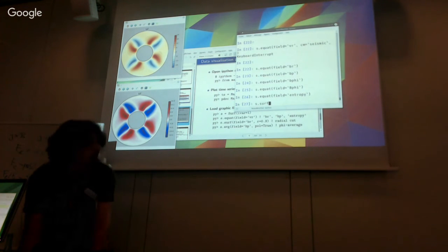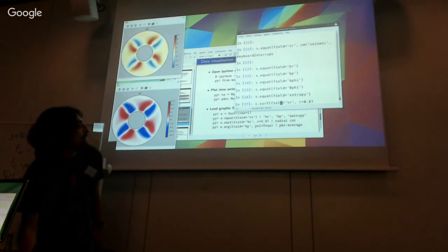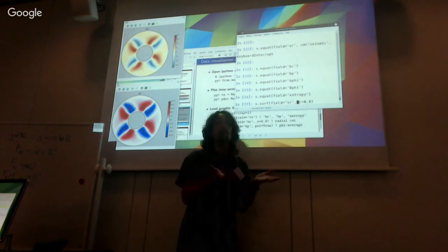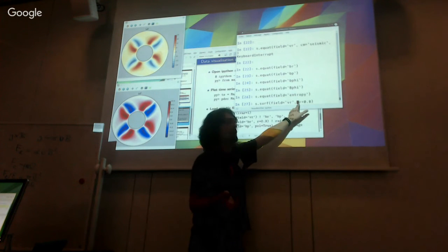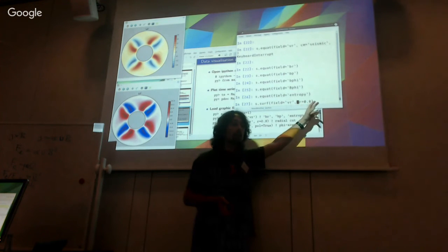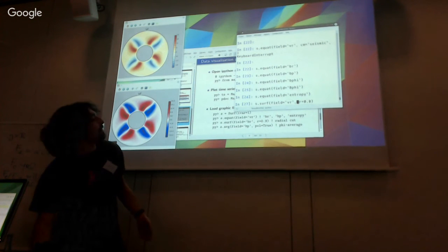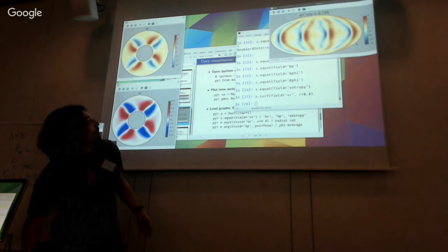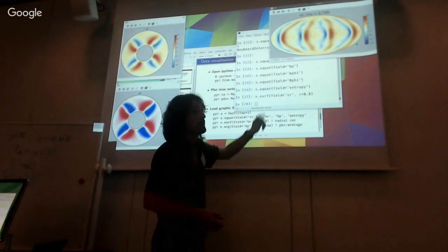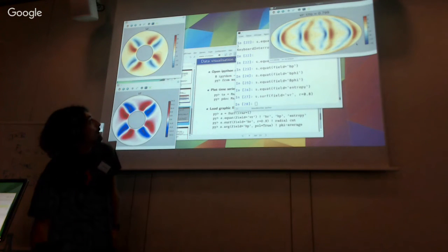The second thing you can plot is the radial cut. So let's do it. Here I plot the radial component of the velocity. I have to specify at which radial level I want to cut, which is the point of this parameter R. This is given as a fraction of the outer radius. So if I put 0.8, it means I'm at 80% of the outer radius. If I put 1, it's going to be exactly the outer radius, so the CMB radius in that case. So you see this kind of plot. Again, we find 4 pairs of columns, with these upwellings and downwellings that we already had in the equatorial cut. Just confirming.